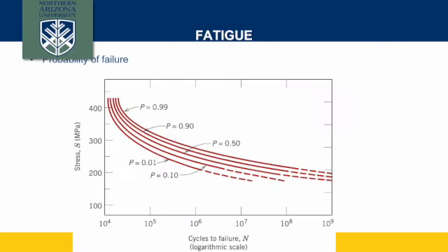So why is this happening? Basically, it's the crack propagation that we talked about. We have voids or natural cracks in the material when we make it. When we fatigue it, we apply and release the stress, and that energy is transmitted to the cracks. The cracks release that energy by getting a little bit bigger, so their a gets bigger. Their critical toughness usually does not. So they start to propagate, and they keep doing that over and over as they're cycled, until the material fails.